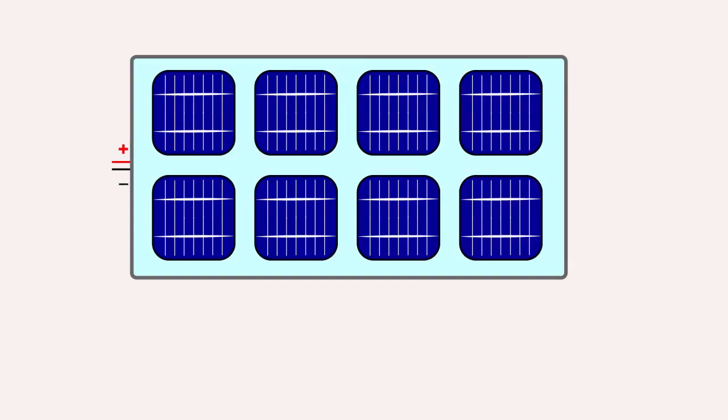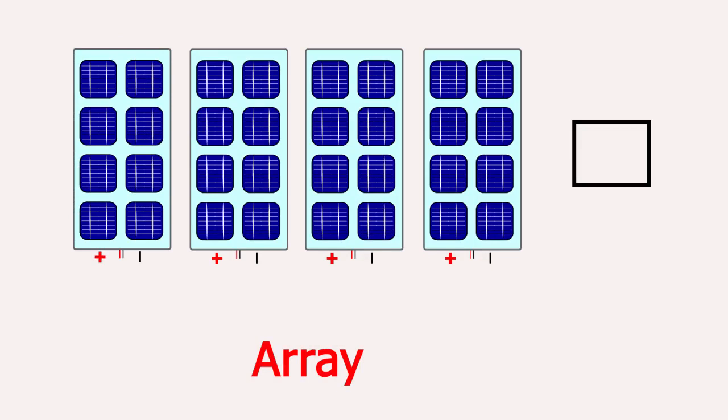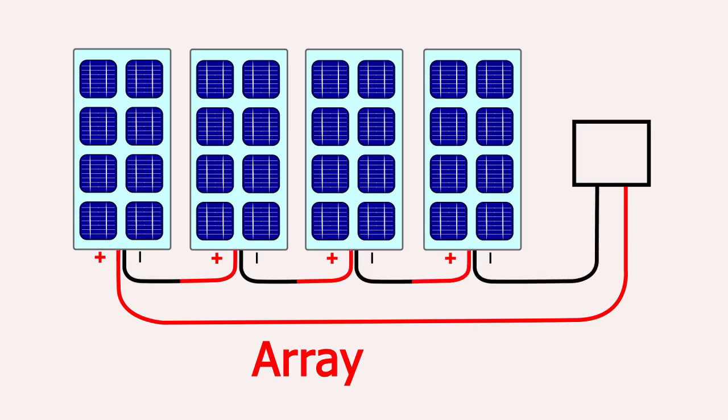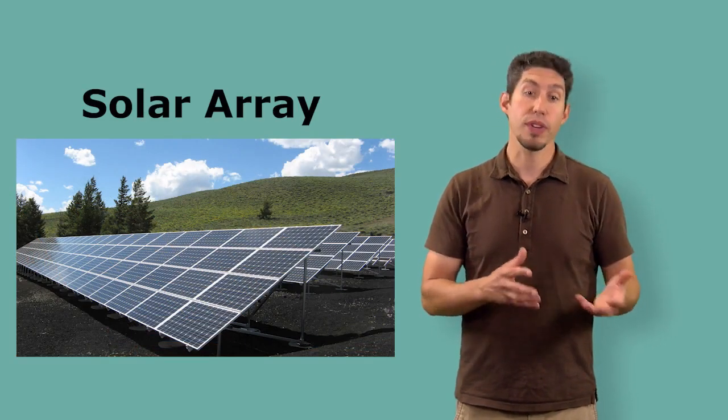When designing a photovoltaic system, photovoltaic modules, also known as panels, will be put together in what's called a photovoltaic array. Just like when the series strings of cells are wired together to make the module, we can also wire modules together in series to increase the voltage of the overall system. In this case, our 4-volt modules would create 16 volts when connected together in series. An array of modules is what you're looking at when you see a roof-mounted photovoltaic system, or even a ground-mounted system.